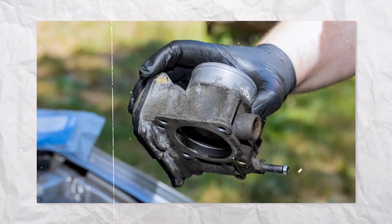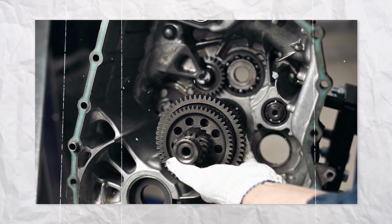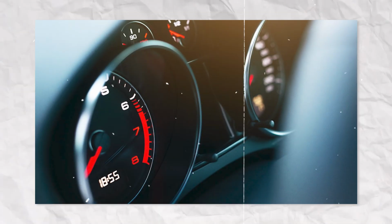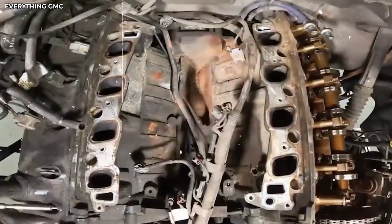The transmission programming works in tandem with throttle learning. If the computer sees gentle throttle inputs consistently, it programs the transmission to upshift as early as possible, sometimes lugging the engine at 1500 RPM in 6th gear on the highway. This saves fuel on paper, but it makes the truck feel sluggish and unresponsive when you actually need power.